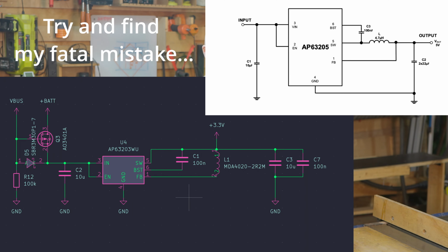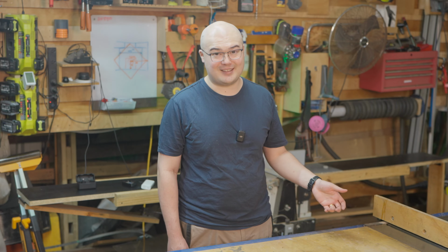Number 2, the entire power supply was miswired and ended up killing 2 boards before I actually realized. So I just ended up stripping out the entire power supply and replaced it with a bog standard regulator, instead of the fancy buck converter that I already had there.